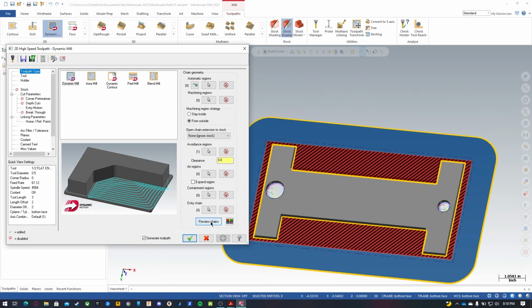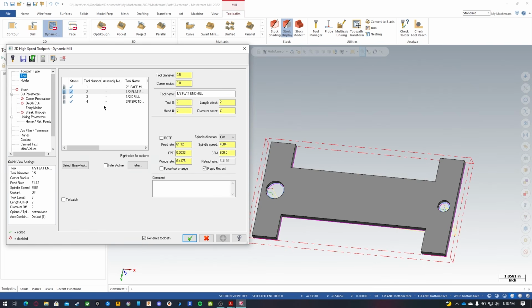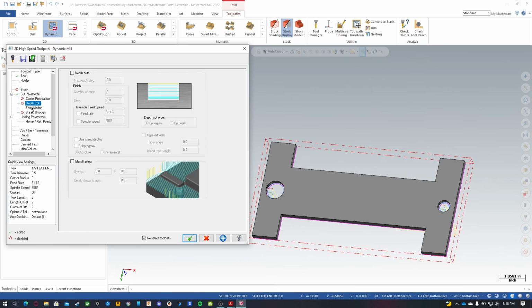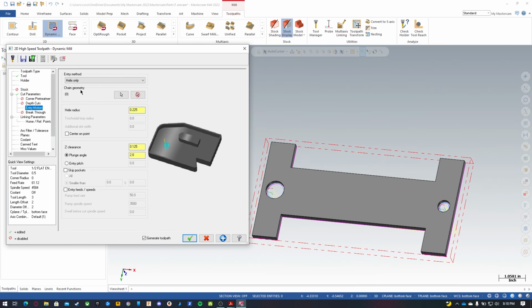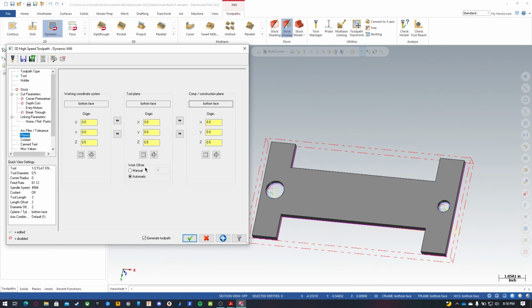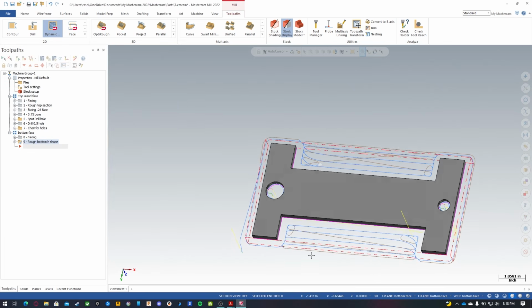So you can click that again to clear it, and we'll go to Tool. We'll use a 1/2 inch end mill. We'll feed at those. We're going to rough the bottom H shape. Go to cut parameters. We're going to leave nothing on the floor, and we're going to leave 50 thou on the walls. Our entry motion is on the outside, so we don't have to worry about this. Planes, we want the bottom base, and we have to specify our depth though.